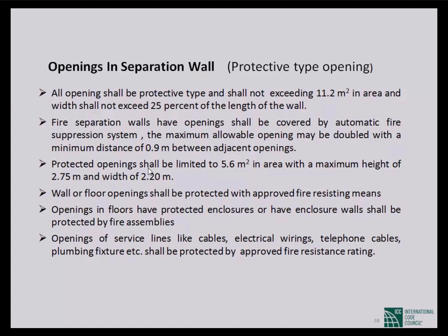By this way you can protect floors vertically. If you have an opening in the vertical direction through the floor, you have to make enclosure walls with fire assemblies.